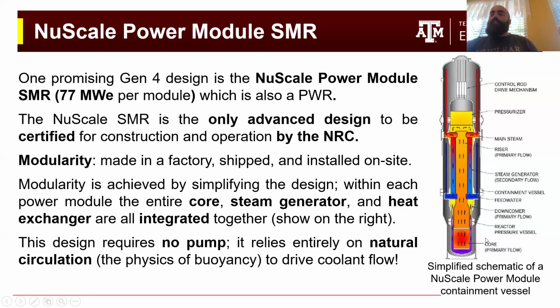And if you look at this core, there's no pump. This design relies entirely on natural circulation to drive the coolant flow. So no pump means you save a lot of money on that pump, and that can help make your design more economical. It also gives you peace of mind, in that if you were to lose on-site power, you would be confident that your system can still maintain cooling, because it can do natural circulation without requiring that pump to operate.